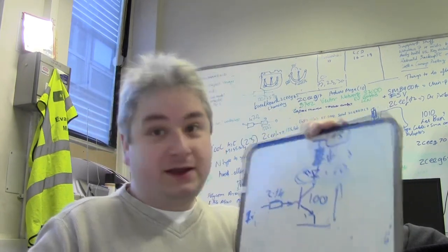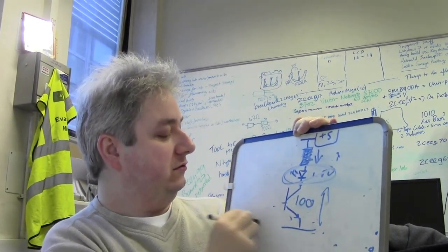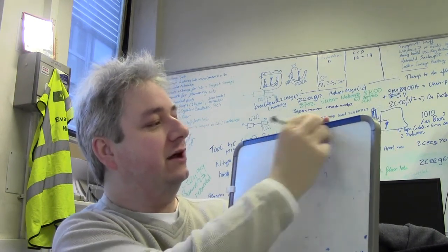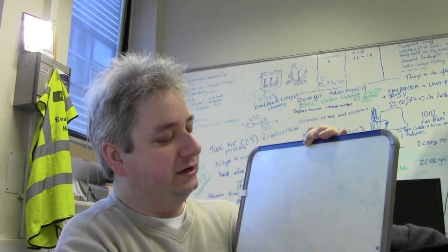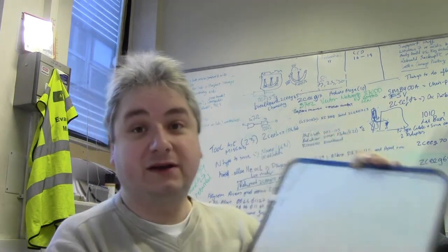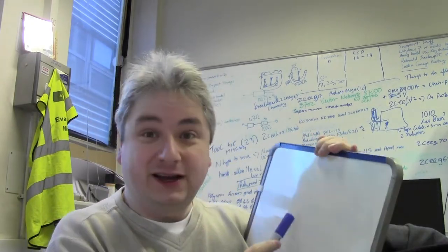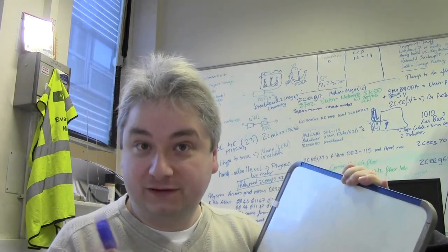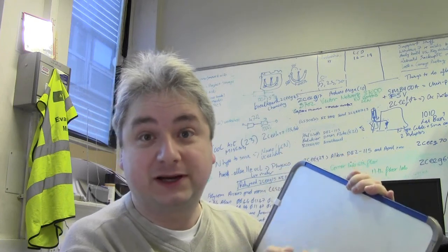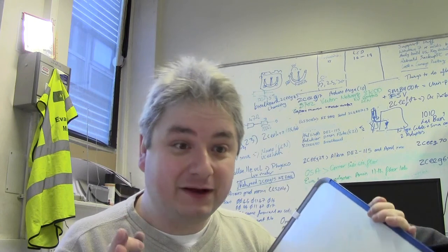So there we go, that's that. That's how you use your transistor to up your 1 volt to a higher voltage to turn on your LED if you haven't got enough power. And that's the same if you haven't got enough current, or enough voltage, either one or the other, that's the way to go. And not only that, you can use that same circuit if you do have a higher voltage, because you can put a higher voltage on the base, work out your currents going into your base and work out your IC and everything. Perfectly fine, and you're not going to blow out your LED either.